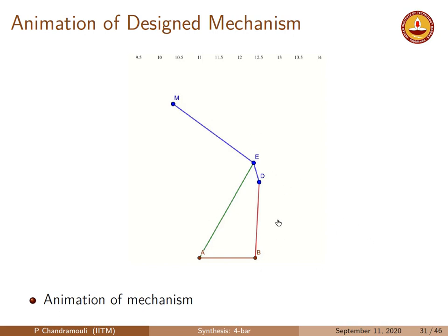So if you go here, I will choose ED and then find out where AB should be, right? We will do a design in that fashion, although that is not a very preferred method of design, as I keep repeatedly saying, because you can't have a fixed pivot at an arbitrary location. It has to be on the body somewhere where it is convenient, like what we have done for the car body here. And on the boot lid, I can have the coupler joints wherever I want.